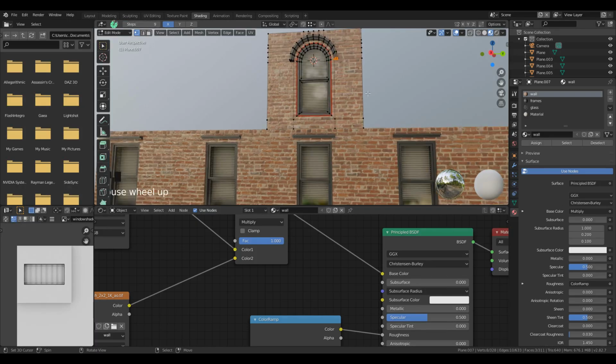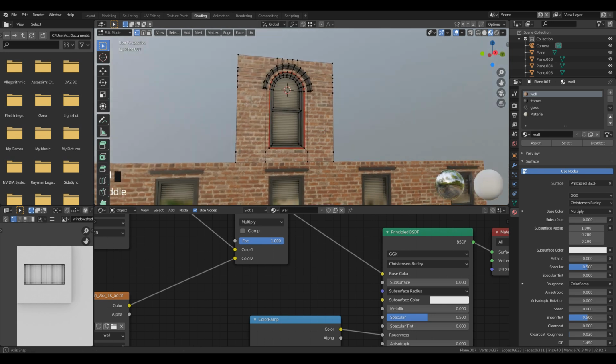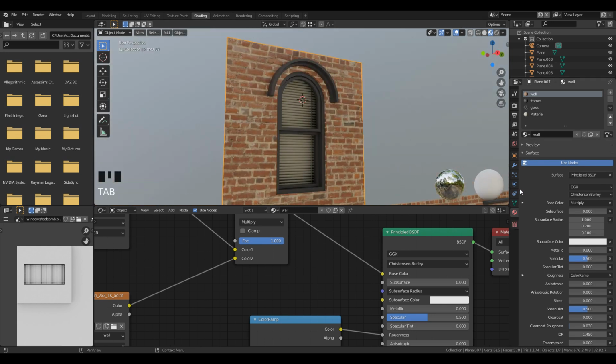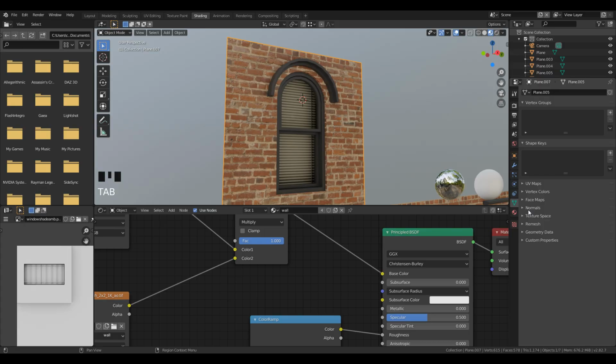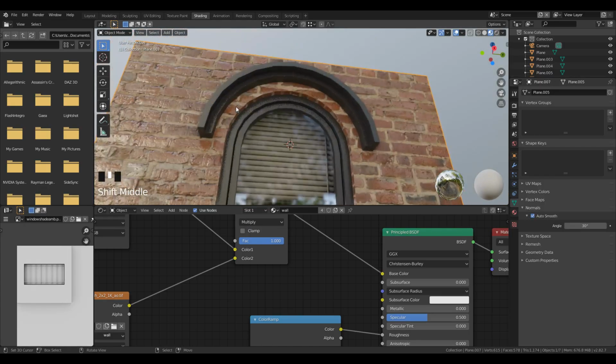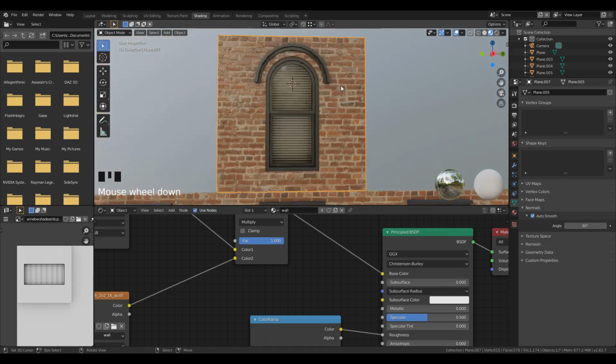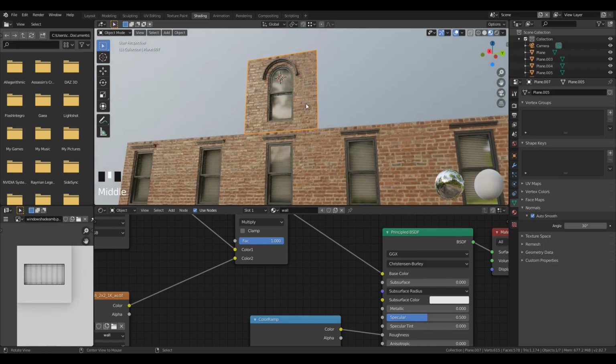In the end, make sure you delete all the reference points, otherwise it will bother you when you try to snap them on the edges of different panels. Then apply shade smooth to it and then auto smooth from the normals to have clean smooth shading inside the curve. Now we just need to create the side panels, or you can say the corner of the building.